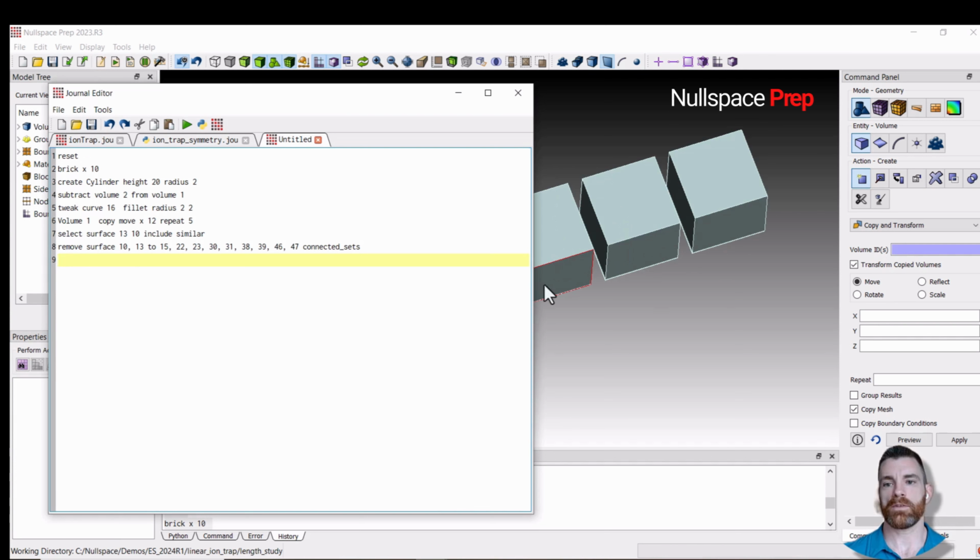And as you're going through, a very typical workflow would be to use the GUI to rough in a design if you're doing a design from scratch, or if you're exploring the best way to do CAD cleanup, to run through different ideas about how to remove features and things like that. And then we just copy those commands into a journal file like this for replay.